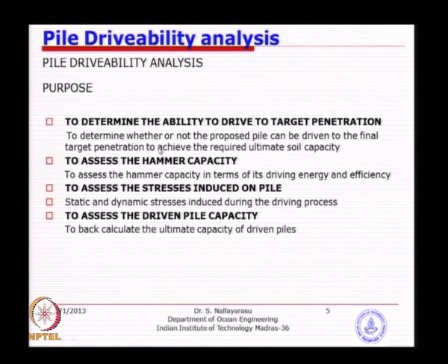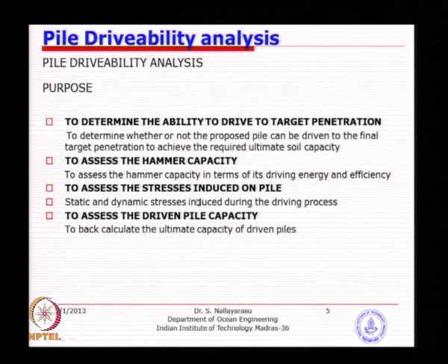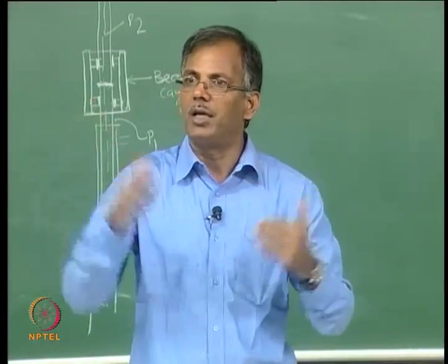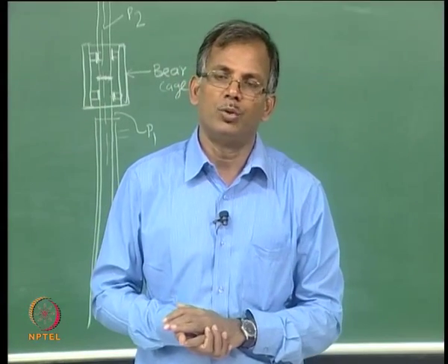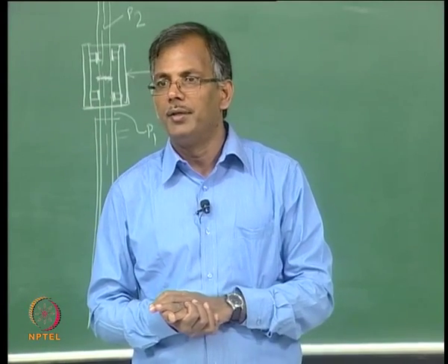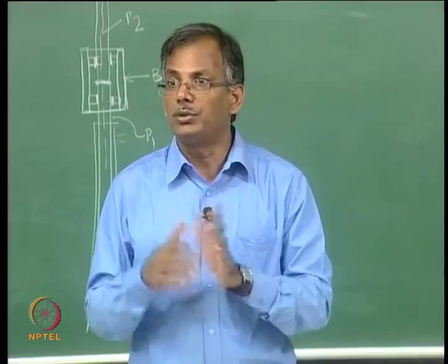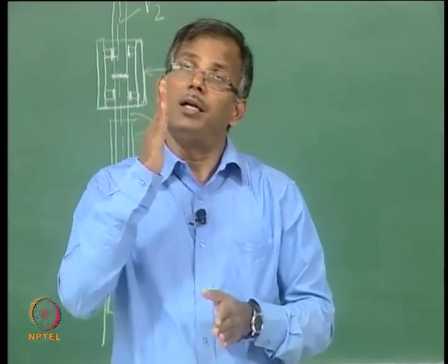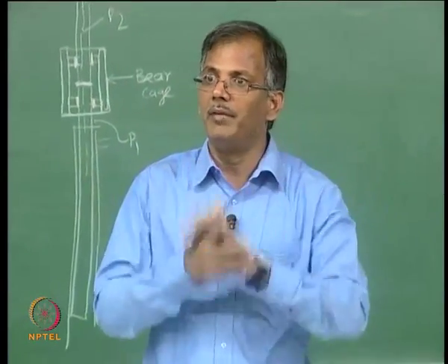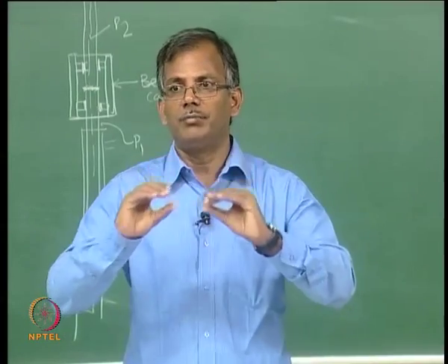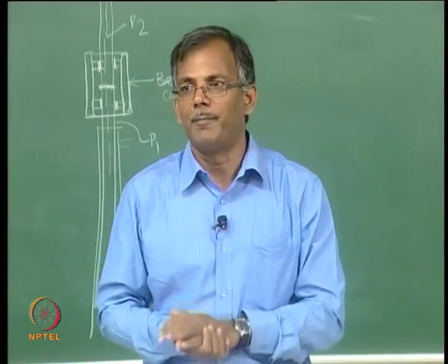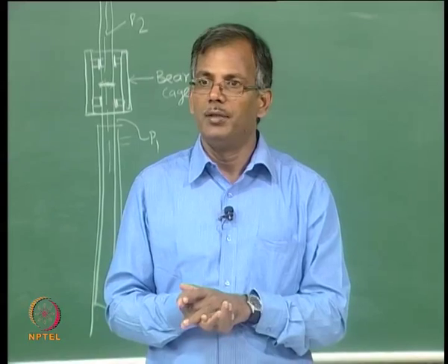So, to assess the hammer capacity means the effort required needs to be evaluated. Stresses induced on the pile during driving need to be kept under control. So, what can be done? Listen, we have ideas to divide the piles according to our so-called flexibility, and that means we can control the stresses to some extent. We do not want 100 meters sticking up, because the bending stresses are very, very large. So, I can divide it into 5 segments, each 20 meters, so the bending stresses can be reduced.